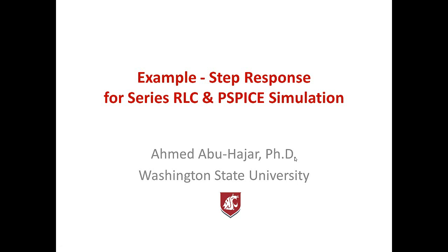In this video we're going to have an example to show you how to solve for the step response for a series RLC circuit. When you solve for the solution of the RLC circuit, you end up with a mathematical expression, and you need to graph this mathematical expression using Matlab. Once we do that, we're going to simulate the circuit using PSpice OrCAD simulation, and we're going to compare the graph obtained from the PSpice simulation to the graph obtained from Matlab, and that basically will verify that our analytical solution to solve for the circuit is correct.